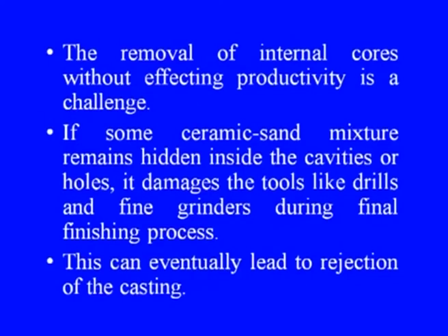First of all, reaching those cavities or profiles or small curves with the cleaning agent itself is a difficult task, and therefore, cleaning the entire mold is a difficult task. The removal of internal cores without affecting productivity is a challenge. If some ceramic sand mixture remains hidden inside the cavities or holes, it damages the tools like drills and fine grinders during the final finishing process. This is another important reason why we should clean it very thoroughly.